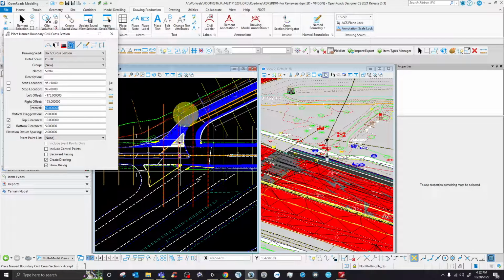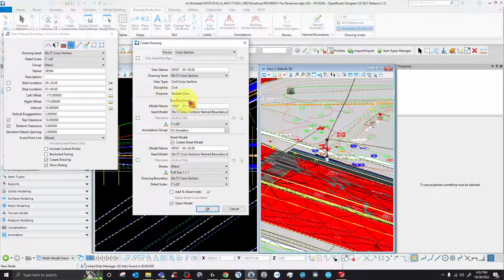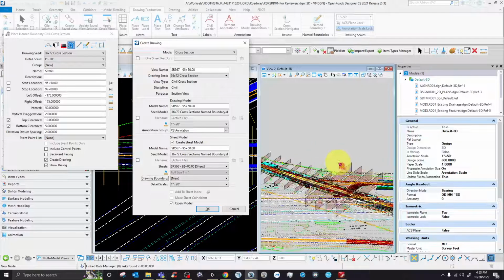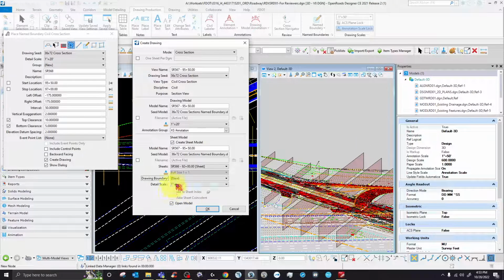So let's cut this tree 4 by just clicking accept, and then gonna show this, make sure 20, 20, these need to match. But now the sheet, I don't want it to create a new sheet, I want it to go to this sheet, which later on I can modify, but automatically we'll just name it as the first cross section station. So now I told it to take this tree cutout, these 3 long ones, to go again to the existing sheet. So let's just click OK.